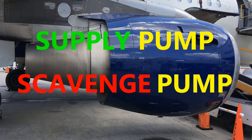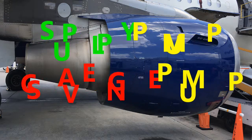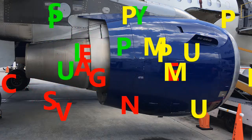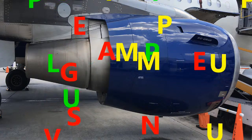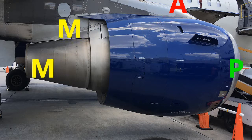Then you have 4 scavenge pumps to bring that oil back. Okay, this is all under pressure, and you have to have a certain amount of pressure. Roughly, I would say about 35 psi of pressure that oil needs to be at, running through the line for distribution to the nozzles that spray those components that need it. For example, engine bearings.